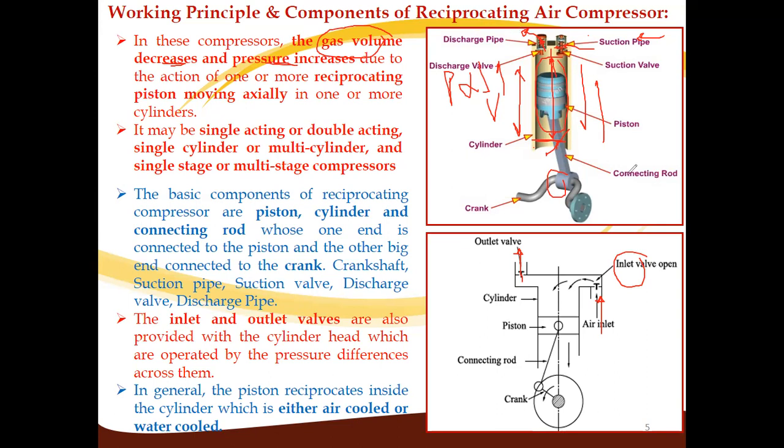The basic principle behind the compressor is that the volume of gas or air decreases and the pressure increases because of the action of one or more reciprocating pistons moving axially in one or more cylinders. It may be a single stage reciprocating compressor, or multi-stage, where in single stage there is only one cylinder, and in multi-stage we have more than one cylinder.